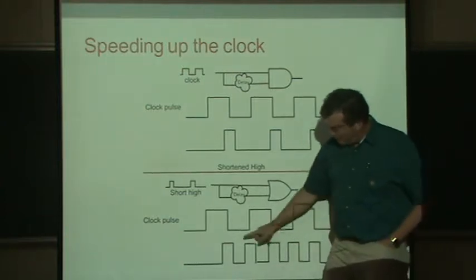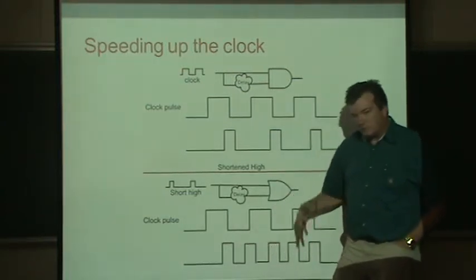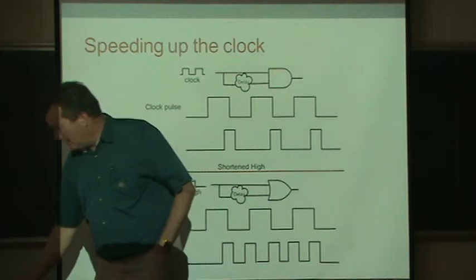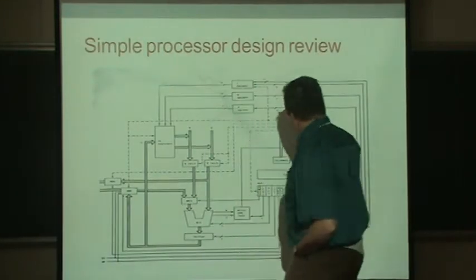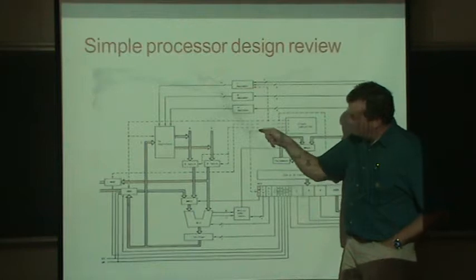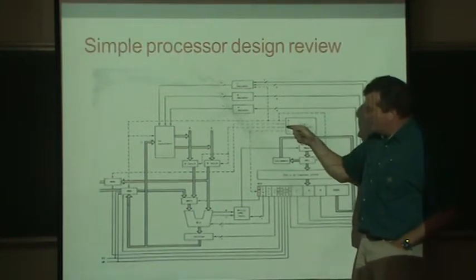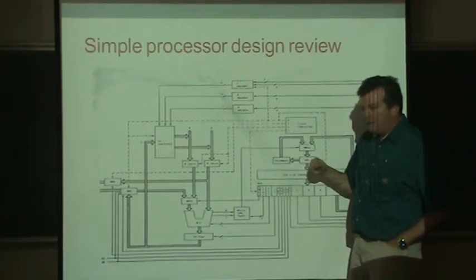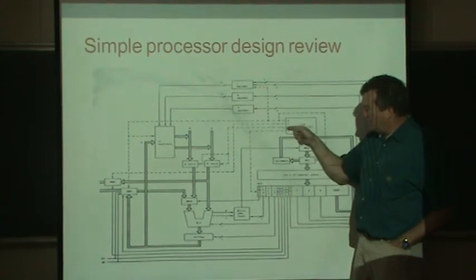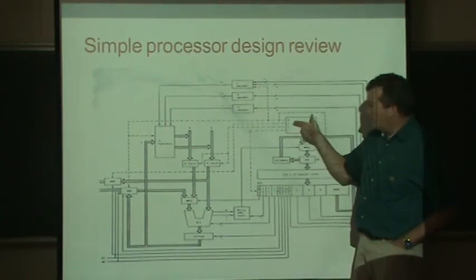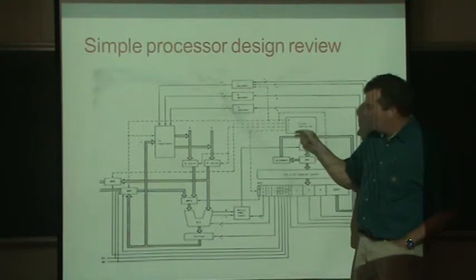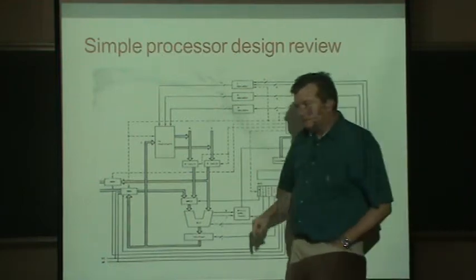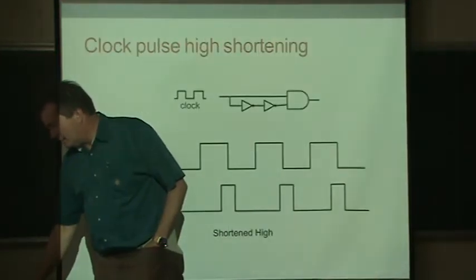And what's going to happen is every time one of these highs happen, once we get it out to 4 billion highs per second, each one of these highs is going to be this clock going. On the first high, this wire turns on. On the second high, this wire turns on. So on the first high, only this wire is on and these 3 are off. On this next high, the second wire is on and the first, third, and fourth are off. On the next high, the third wire is on and 1, 2, and 4 are off. And we're going to just keep going 1, 2, 3, 4, 1, 2, 3, 4 every time the sped up input signal hits a high.